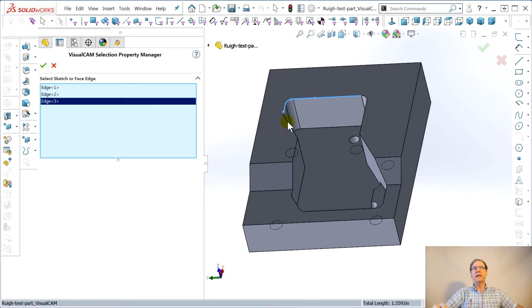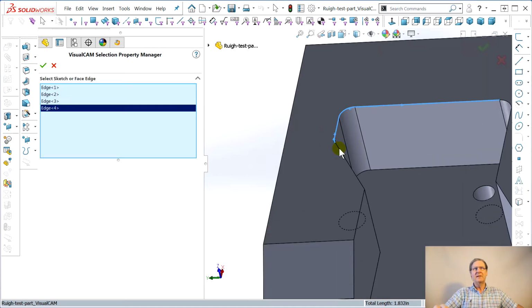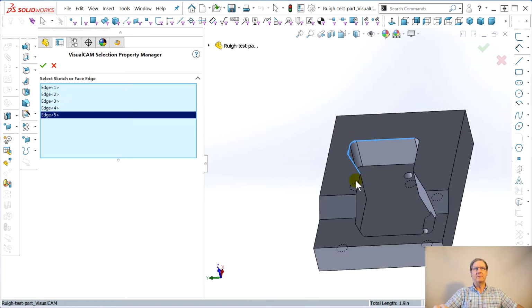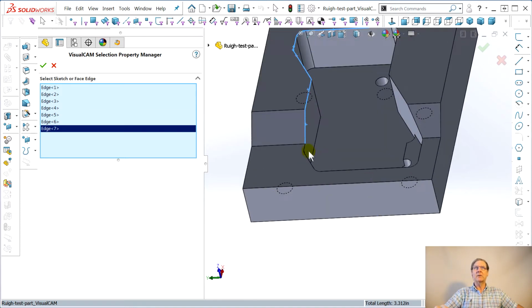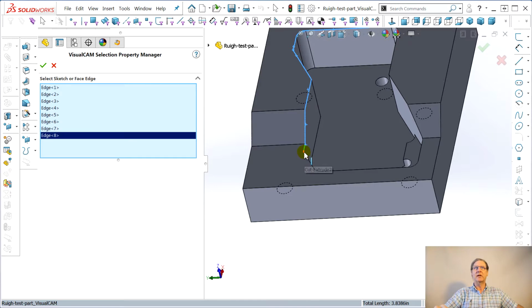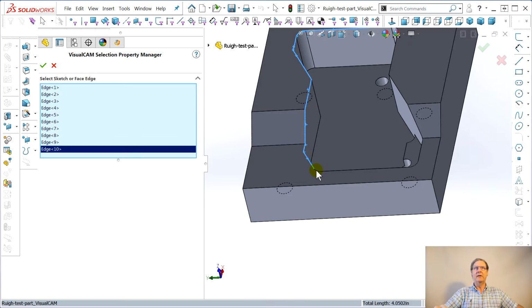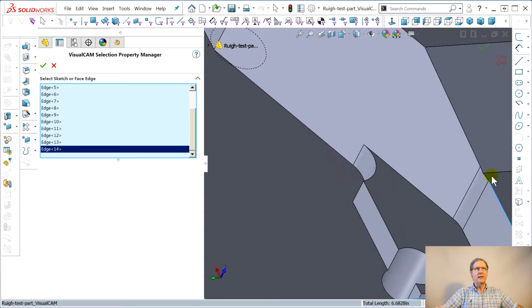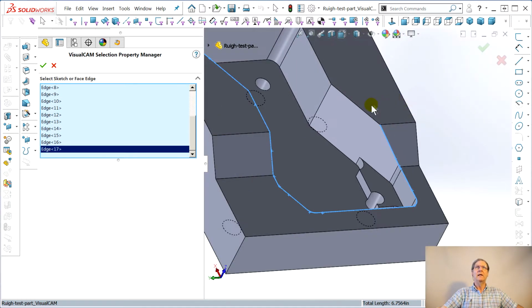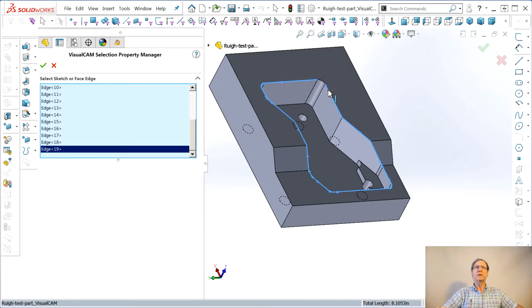Unlike SolidWorks CAM, so you can see I've done this so many times, I've memorized all the little hiccups. Unlike SolidWorks CAM, it doesn't show you a little darkened blue outline of a closed profile, which is darn handy. I had this one blow up right here where there's not only this little fella, but this one there. And you go here, and you go here, and you go here, and that's a closed contour, I know for a fact.